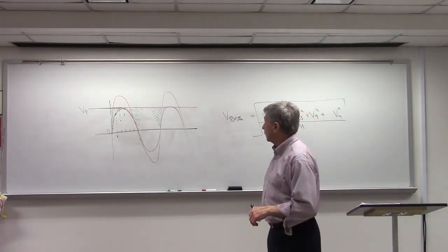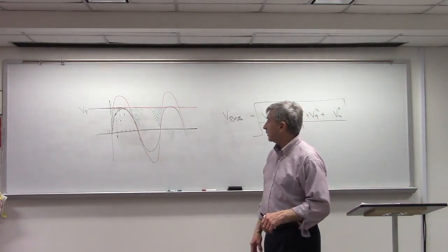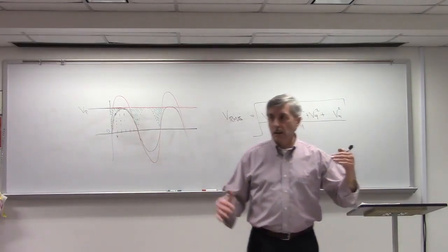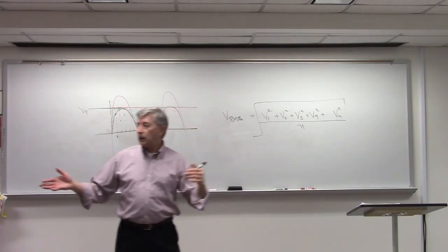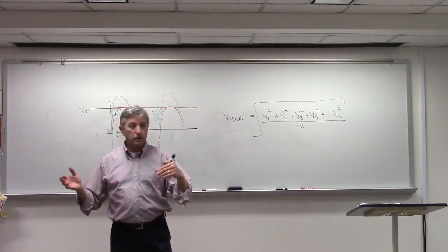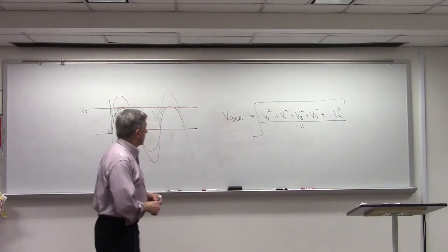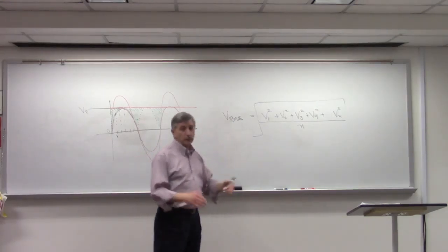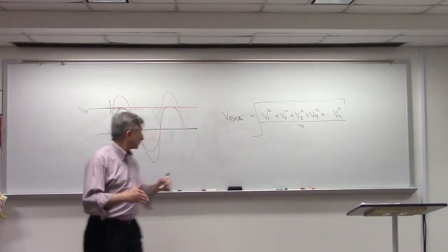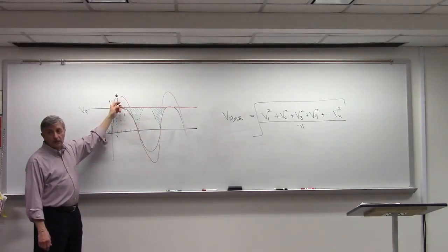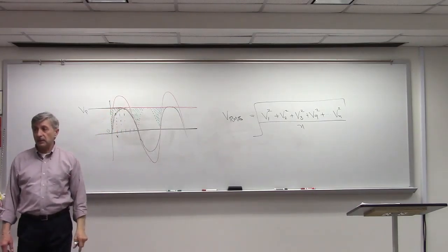So the question is, what is the RMS value? When you take a reading of an AC outlet, a receptacle outlet, you get what, 120 volts? And that is always RMS. What you're reading is root mean square. But the peak value for an RMS voltage of 120 volts is somewhere around 170 volts.